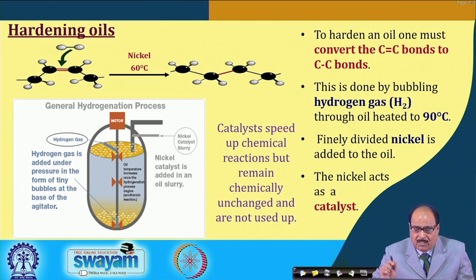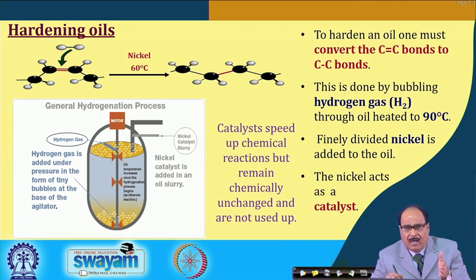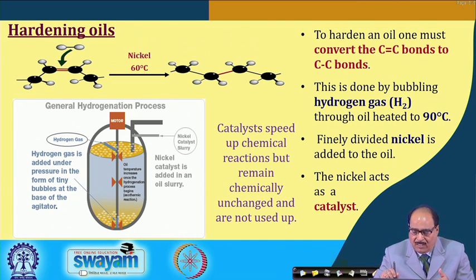So, these different things take place. Here in this slide again we have shown a hydrogenation system in the process, that is the equipment. It is basically a reaction vessel, a hydrogenator. In that reaction vessel it is equipped with all the necessary instrumentation and other accessory facilities for making the reaction take place, that is, for addition of the hydrogen, providing suitable temperature and pressure, and a system for catalyst additions.